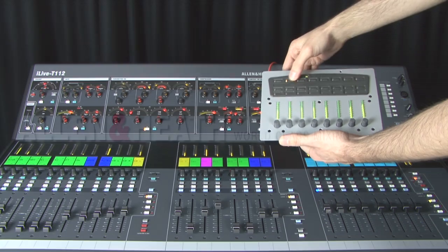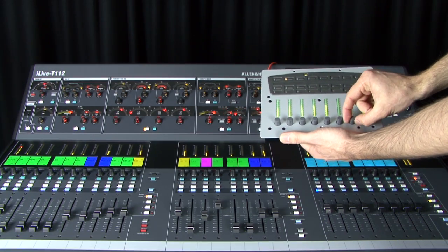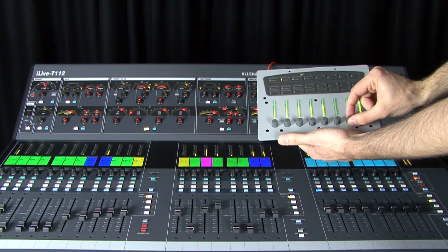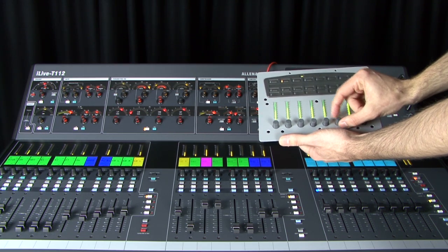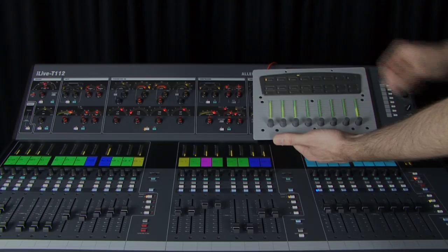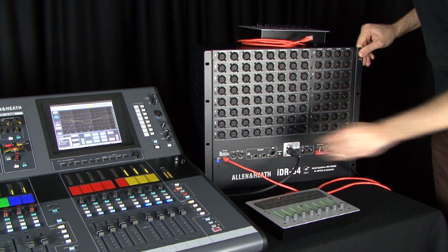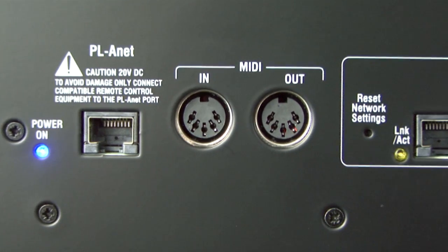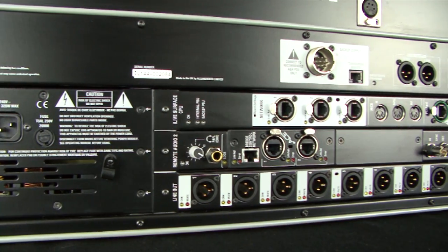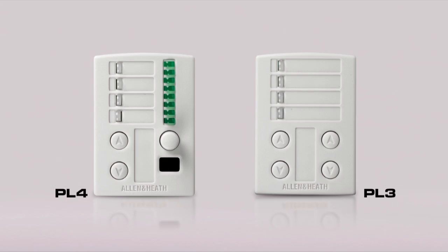Allen & Heath PL remote control devices provide controls such as faders, rotary encoders, switches, indicators, and logic GPIO, which may be assigned by the user to suit the application. These controllers interface with iLive using standard Cat5 cables via the RS485 based PL-Anet port on mix racks and modular surfaces.